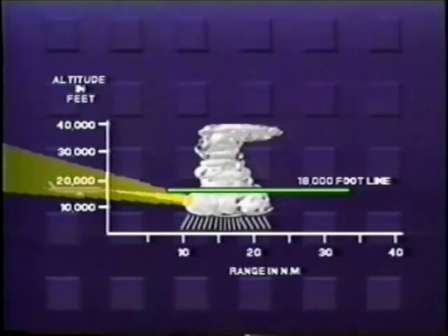Coupled with a requirement for good tilt management skills is a requirement for good range management skills. Range management means to choose the radar display range that is proper for your flight altitude. If your flight path is below 18,000 feet AGL and you use the recommended tilt management procedure, you can use any display range and not be in danger of overflying a dangerous storm. In that case, simply select a range which will give you adequate warning time so that you can make an avoidance maneuver in a timely manner.